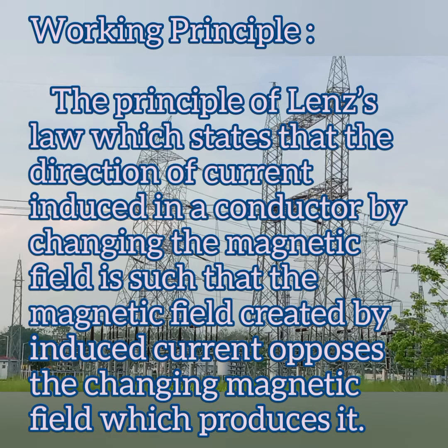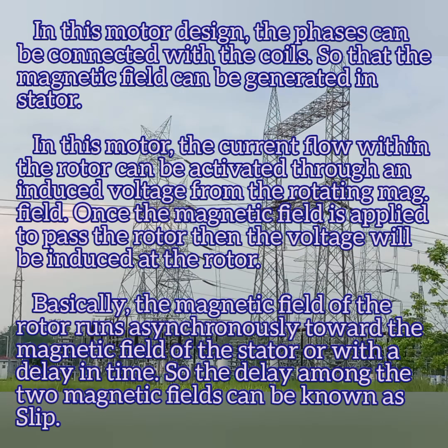Then the working principle. The principle of Lenz's law, which is followed by this asynchronous motor, states that the direction of the current induced in the conductor by a changing magnetic field is such that the magnetic field created by the induced current opposes the changing magnetic field that produced it. So the stator magnetic field and the induced rotor magnetic field oppose each other.